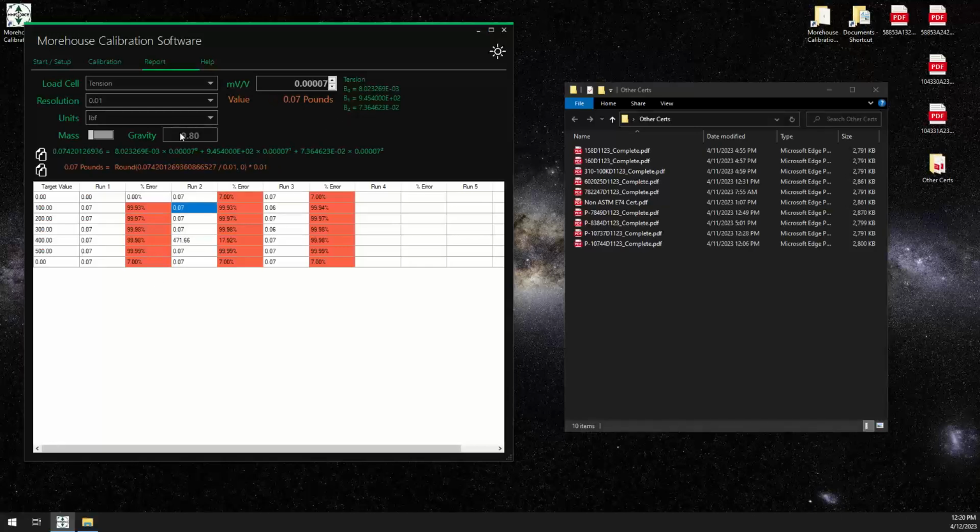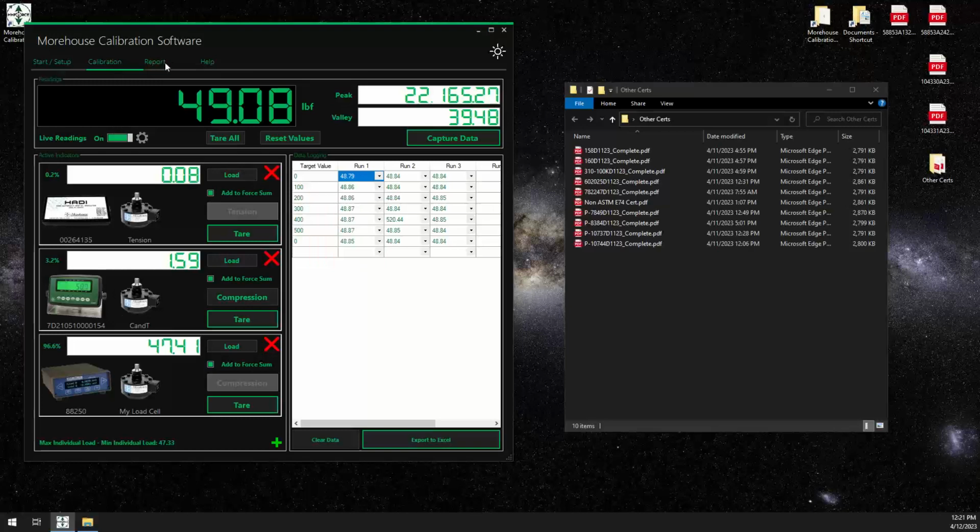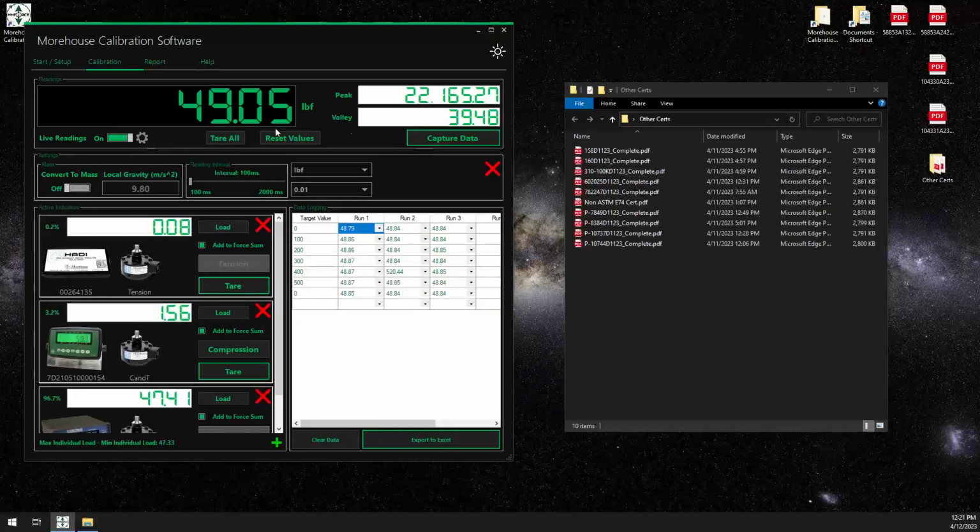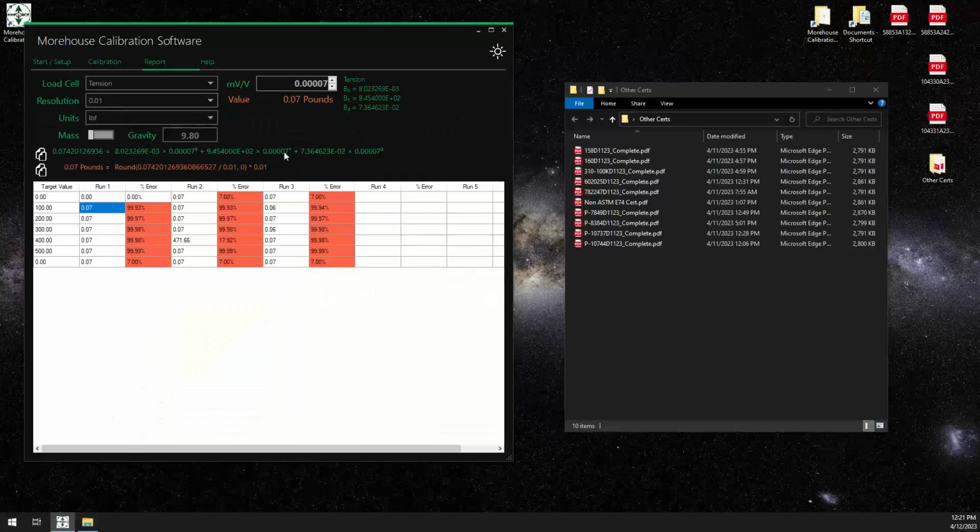It is rounding. Where you would probably use this is if you have an unstable situation with power and you say, look, my numbers are just erratic all over the place. It's just easier. I want my millivolts per volt to be steady, and I change it to read by 2 microvolts, 5 microvolts, or even 10 microvolts. That would be a situation. But then that really messes you up on your uncertainty and what you claim if you're calculating uncertainties correctly. So I really try to stay away from that.